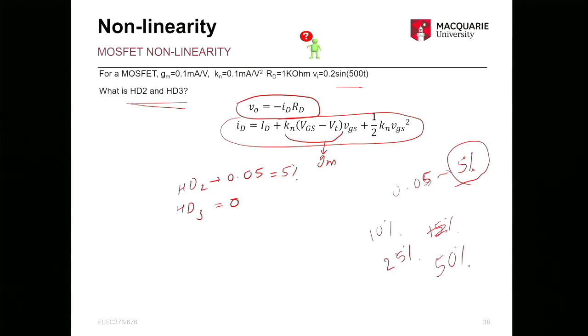So that is in the BJT. That is because we take it at the collector through the resistor. So the same thing happens: when you increase the voltage, the output current is increasing, and when you decrease the input voltage, the output current is decreasing. But when we take the voltage output, that's the reverse. When you increase the current at the output, more voltage is dropped across the resistor, and you're getting only what is remaining. Oh, yeah. Right.